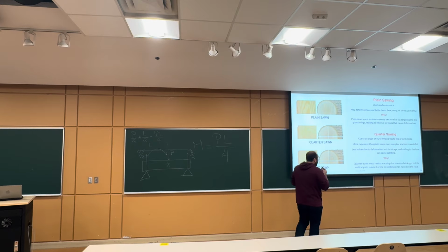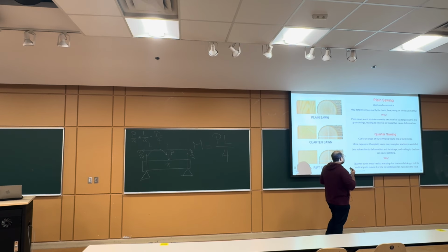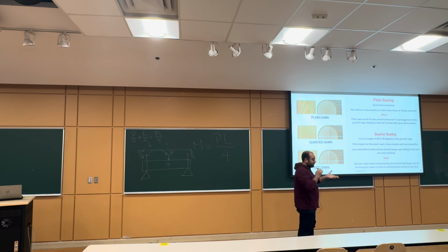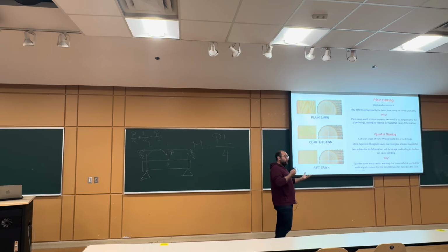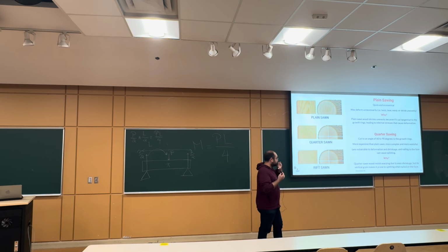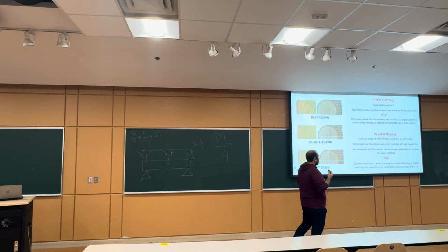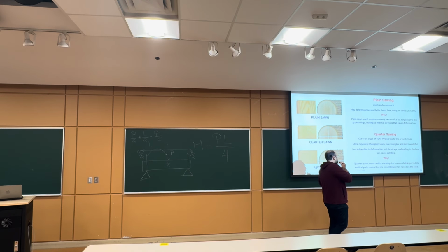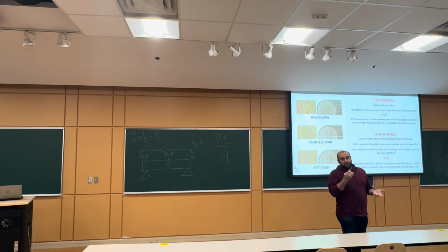So, why is this actually very efficient? As we said, quarter sawn wood resists warping or any surface or depth deformations due to even shrinkage over the whole cross section, but its vertical grain makes it prone to splitting when nailed on the face. So this is the difference or the problem that we might face. Any other question?